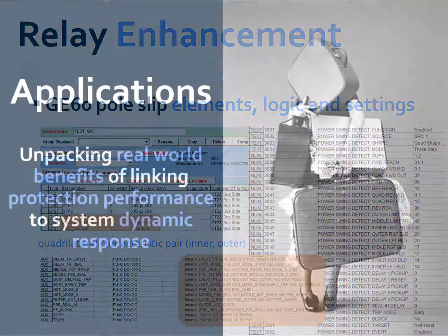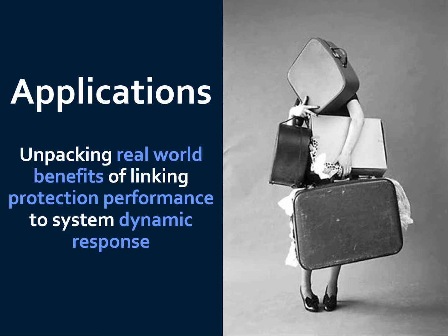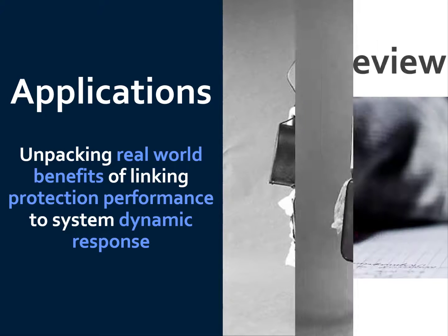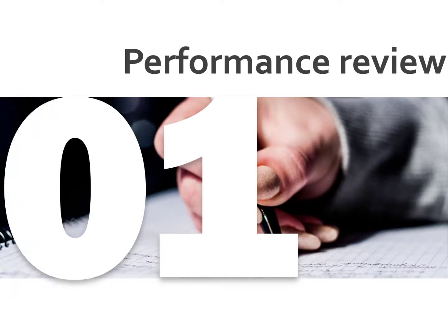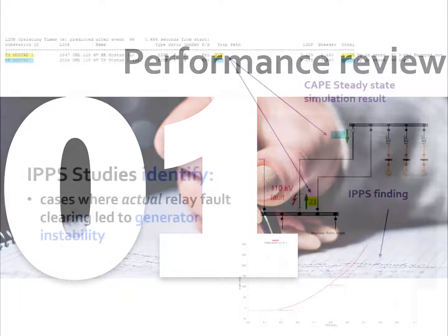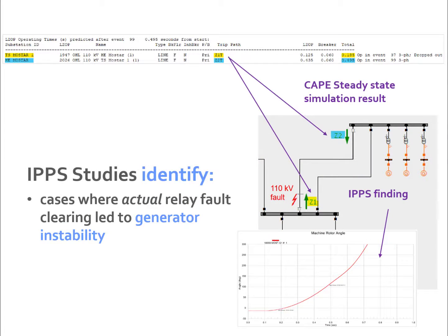common relay. So what then are the potential applications for IPPS environments? With the frequency and the nature of changes occurring in today's power systems, periodic reviews are required to ensure secure operation is maintained as electrical centers move and power swing speeds increase with reduced synchronous machines online. With IPPS environments, instances where selective fault isolation exceeds critical clearing times can easily be identified.